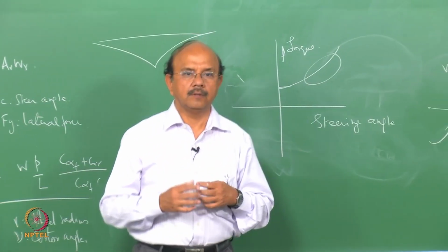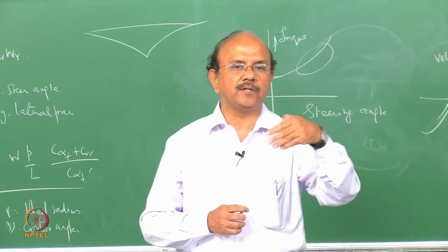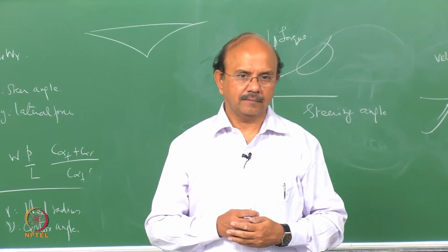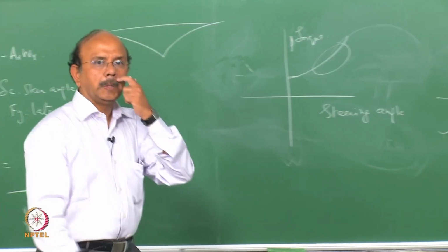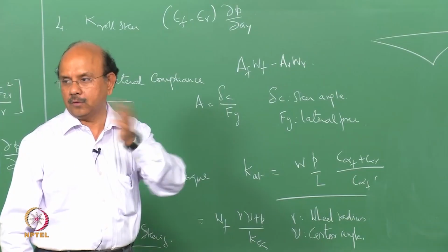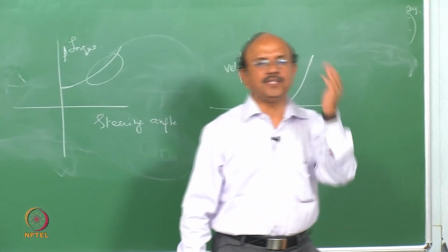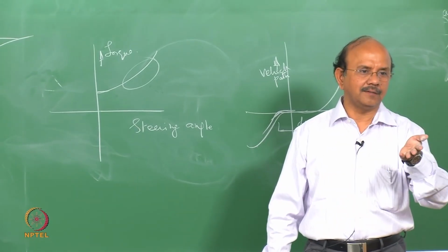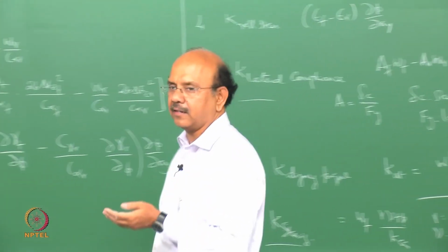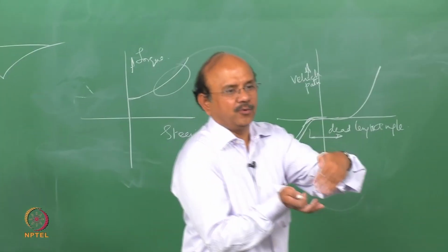So when you're plotting the vehicle path, what does it actually mean over here? The path you want to take, usually the path is measured by the nose angle to your path. How much is the nose angle different from the path you want to take? Deviations. That's it. You can plot the deviation as an angle, the nose angle. As I told you, when I say there's a path and deviation from the path, we talk about the nose angle. Even when you look at the understeer or oversteer characteristics of the car, we look at nose angle. Nose angle is simply the attitude of the car.